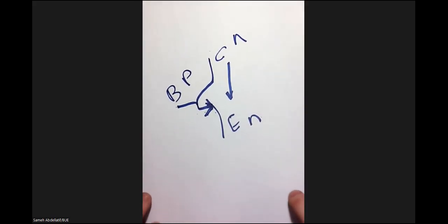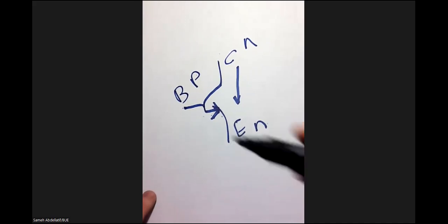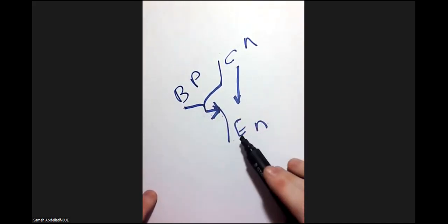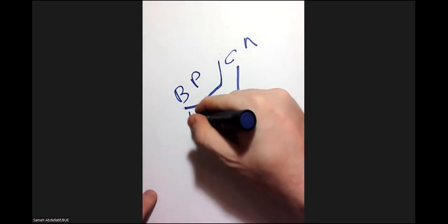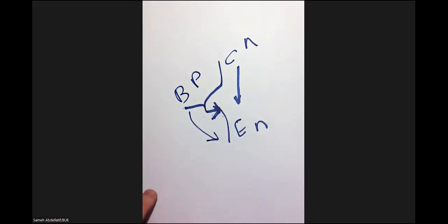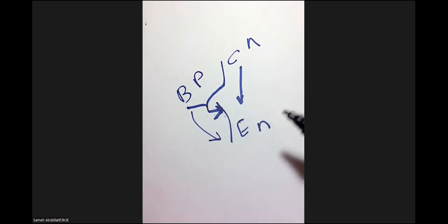For NPN, the condition of operation is related to the base-emitter junction. You have to apply a base-emitter voltage VBE which is equal to or sufficient for the built-in voltage of this junction, which is roughly 0.7. So this VBE should be 0.7 in order to operate. In other words, the voltage of the base should be higher than the voltage of the emitter by 0.7 in order to operate. And this includes two regions of operation, either the active region or the saturation region. I think we already spent some time to understand this in class A power amplifiers.